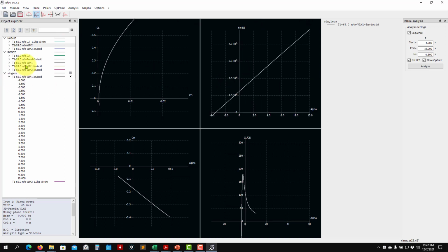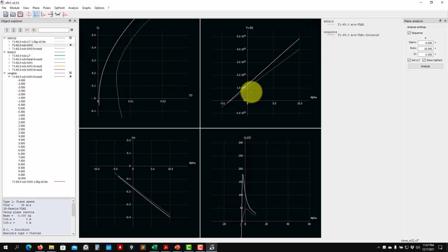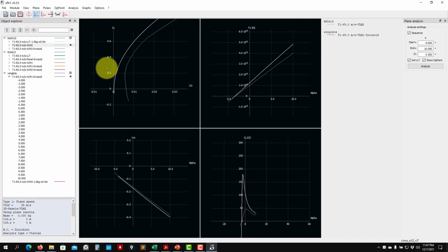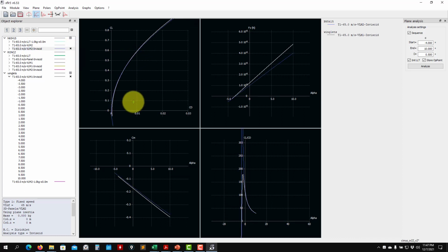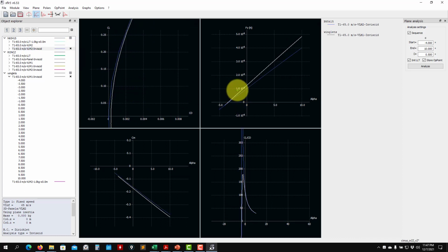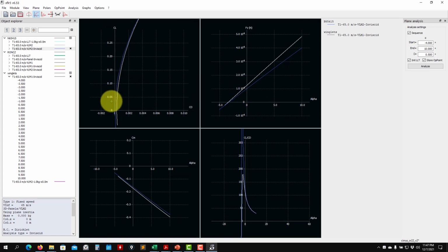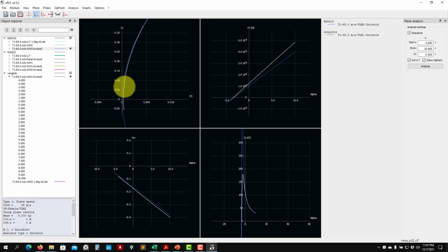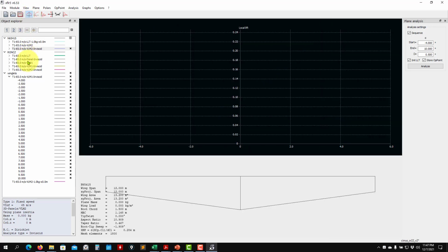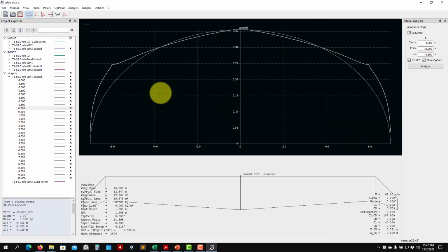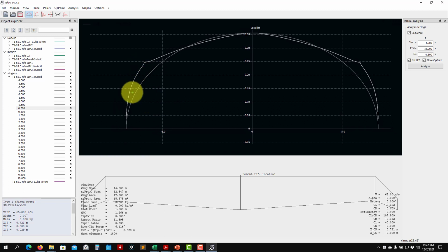So you can then run with no winglet. Okay, let me show. So see the influence. The winglets have this influence here. So let me see what happened. Okay, it should be this one that I should compare. So adding winglet has the effect of increasing lift. It will increase the drag because you're increasing lift, and remember that induced drag is a byproduct of lift, but you are increasing lift because you are effectively modifying the lift distribution. So this is the effect of the winglets.